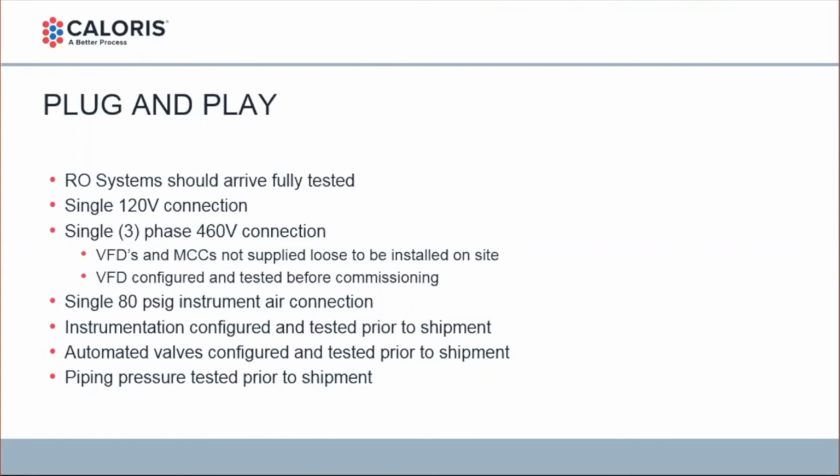It should have a single 80 PSIG instrument air connection. The instrumentation should be configured and tested prior to shipment. Automated valves should be configured and tested prior to shipment, and you should have the piping pressure tested prior to shipment.